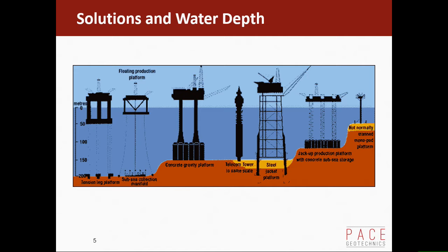It's got skirts on it around the sides of the storage tanks that go 25 metres into the seabed. Now, you're not going to get 25 metres with a small structure. But that helps give it lateral capacity, so you push them in, and that gives you immediate lateral capacity, which is what you need.